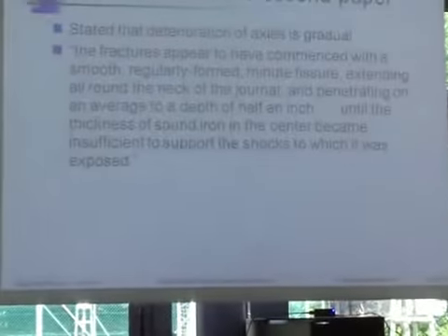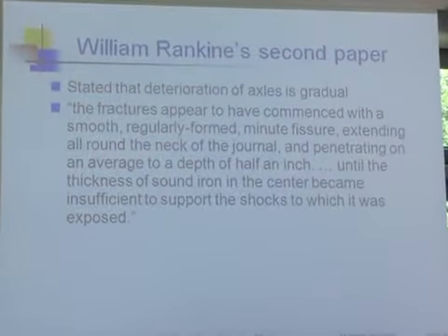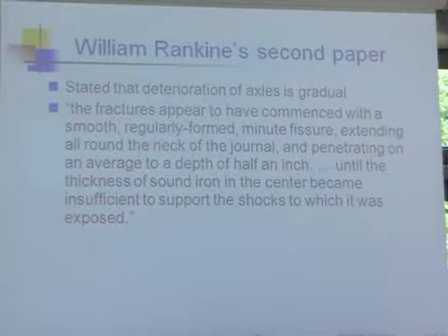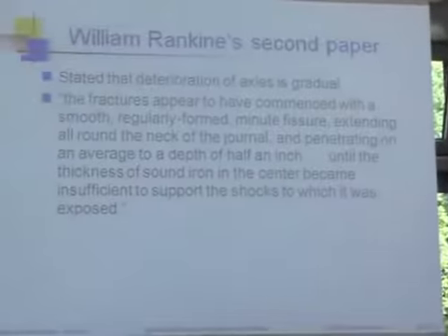And then the thickness of sound iron in the middle was insufficient to support the shock loads to which it was exposed. Pretty good description. Even today, if you were to write the description of a fatigue failure, this is it. The only thing he didn't know was he did not have any idea about our modern concepts of fracture mechanics and the importance of the crack, other than to know it was there and it grew slowly.